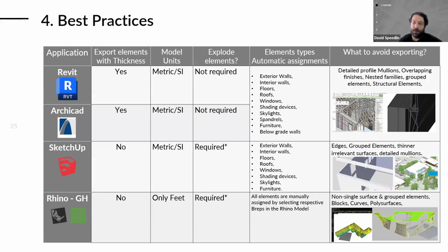that are not locked, grouped, blocked, or in any other way connected to a solid or combined with any other geometry. Units must be in feet. Only geometry on Cove tool layers will be referenced. Delete all bad objects and purge unused file elements. Ensure all surfaces are facing the correct direction with the front face facing outward or upward. All geometry should be in the X and Y plane, and only geometry above ground should be exported.